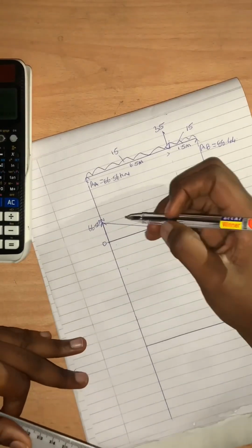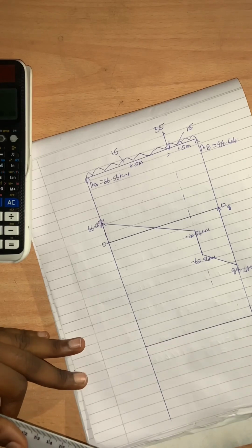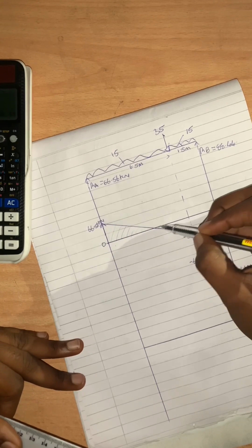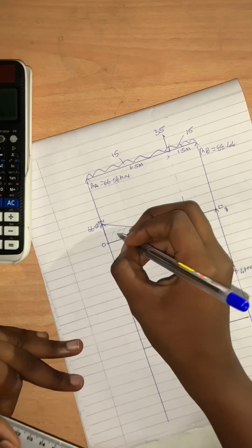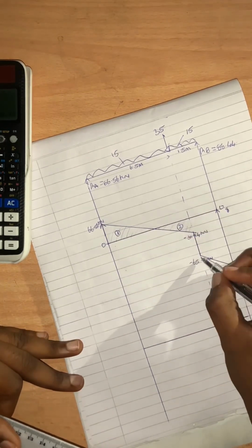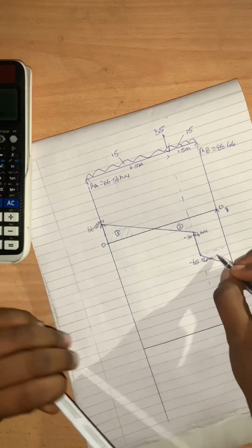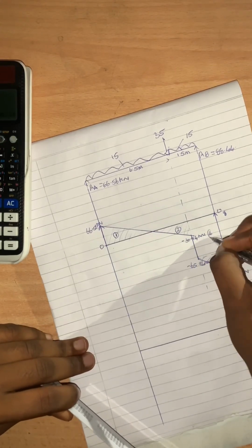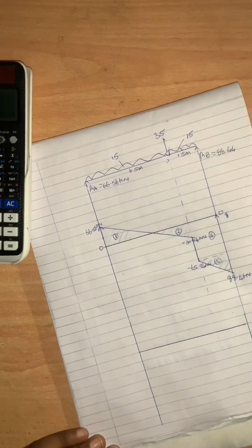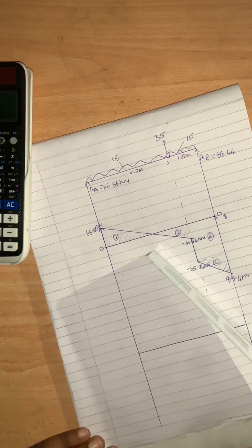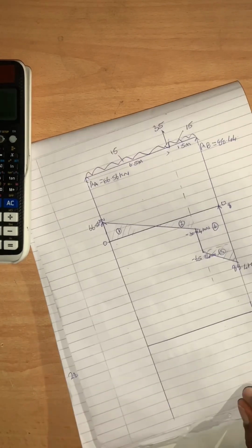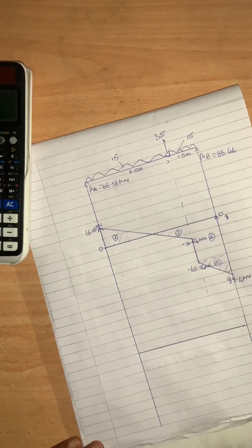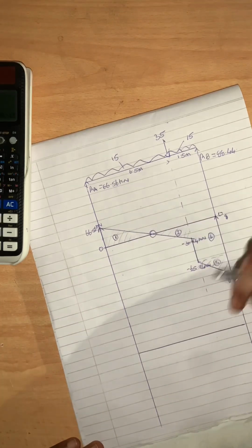Because even when you are drawing your moment diagram from your shear force diagram, you calculate the area of the shapes. Then this is a triangle, so this is triangle 1, this is triangle 2, this is another triangle here, triangle 3. We're going to be doing it step by step, and this is a square, which is number 4. So this is going to help us in drawing our bending moment diagram. But the main thing that we need is the maximum moment, and you know that when shear force is equal to 0, you have your maximum moment.